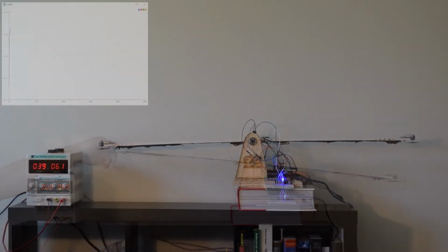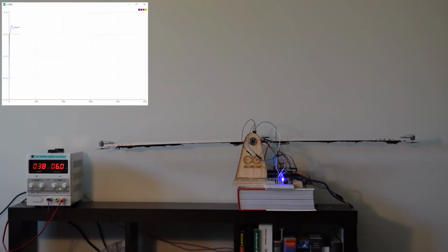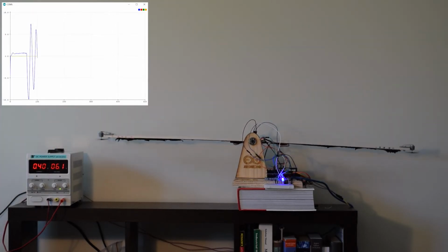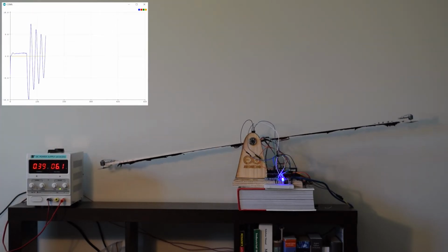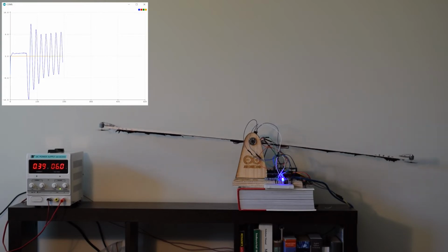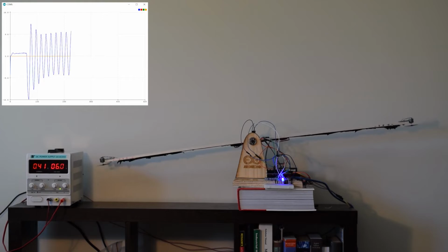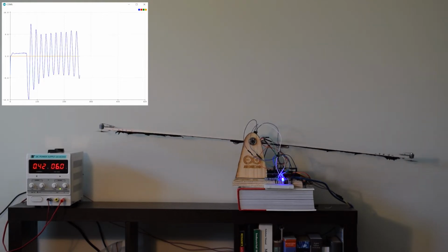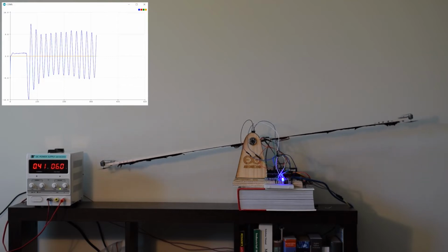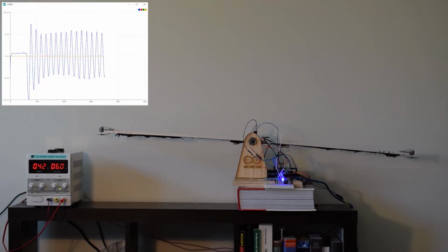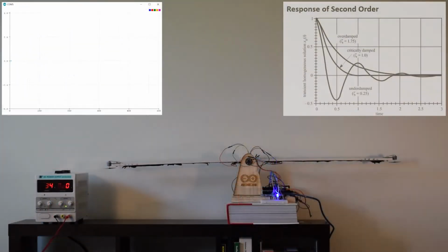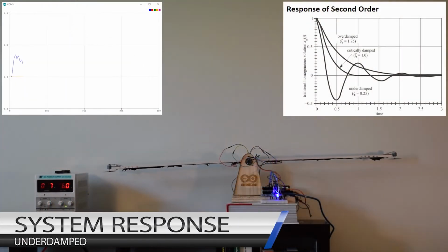When tuning the PID gains, I had a little difficulty determining the Kp at which sustained oscillation occurred. To overcome this, I printed the angle data to a serial plotter which allowed the point at which sustained oscillation occurred to be easily found. I then measured the period between these oscillations using a stopwatch, and used these values in the Ziegler-Nichols equations to determine my Kp, Ki, and Kd gains.